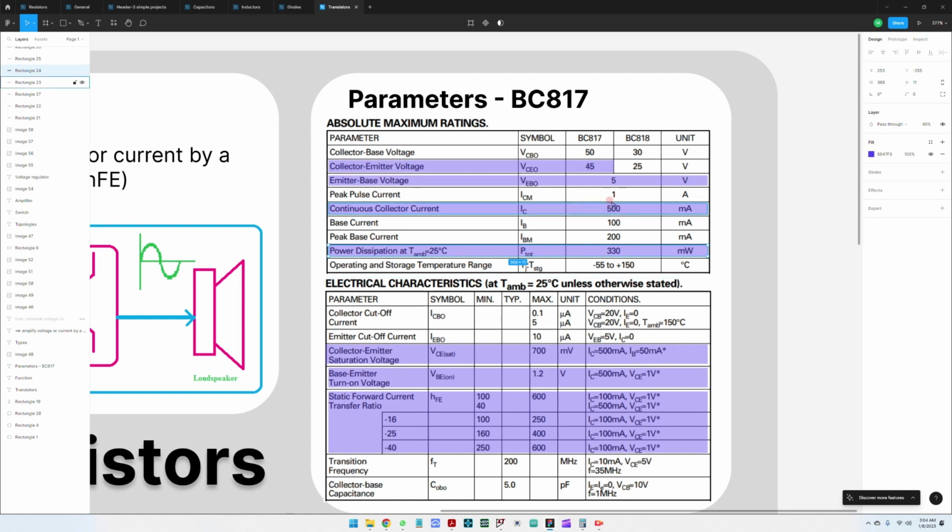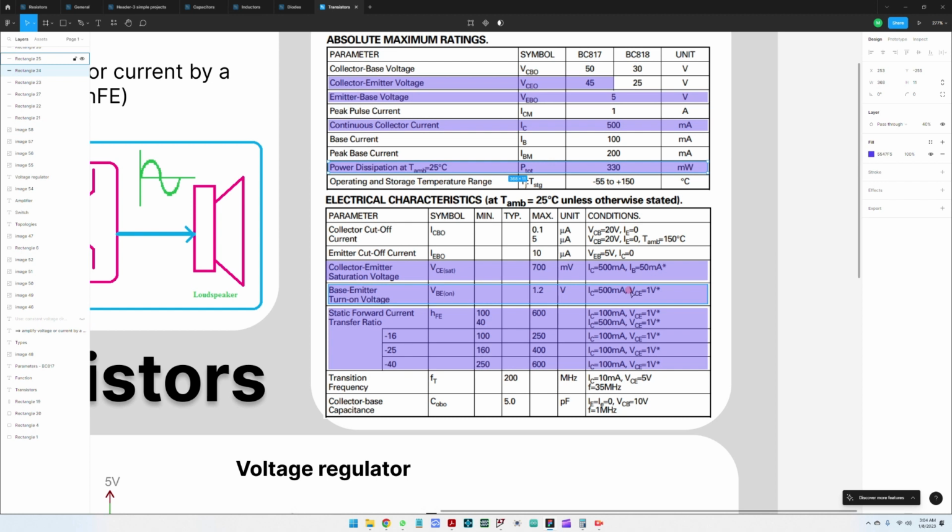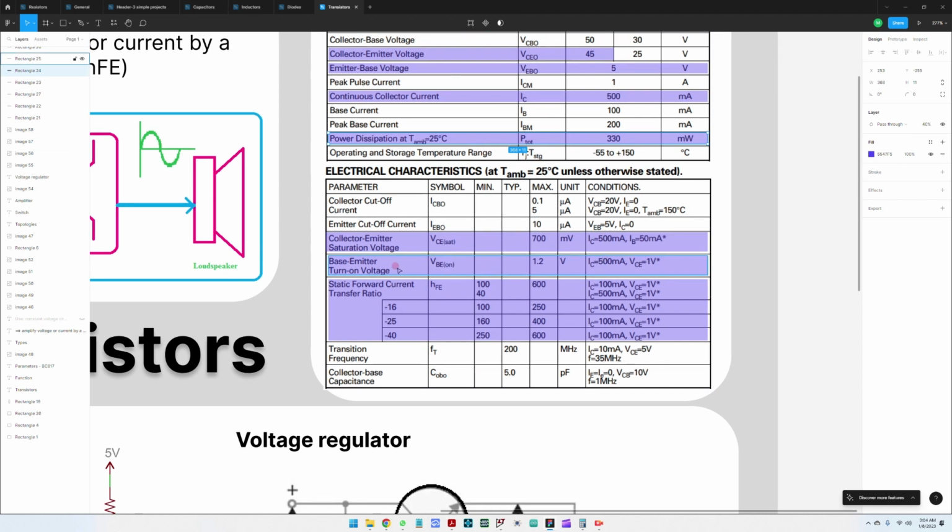At max current we need to calculate so that the transistor doesn't have more voltage than would exceed this power dissipation capability. And please always leave 20% of this total power in reserve, so that the component is not damaged and you're not working at the very edge of the specification for the component.